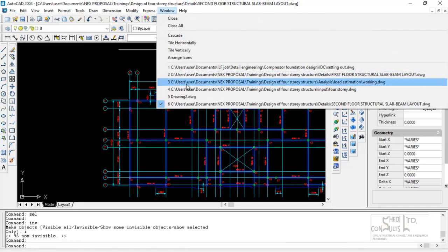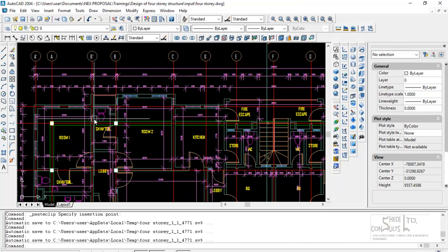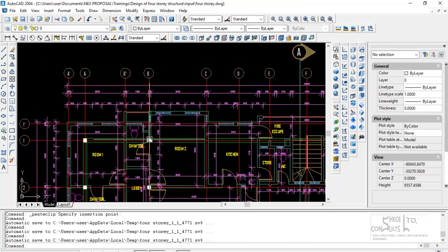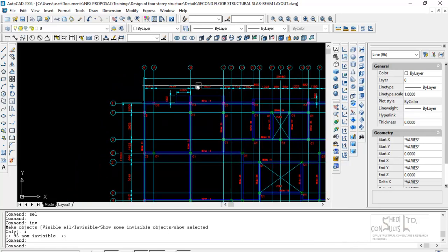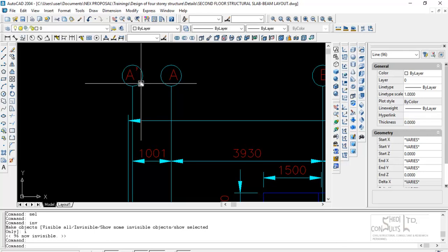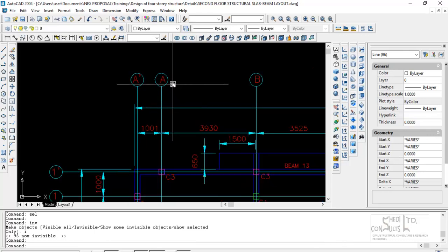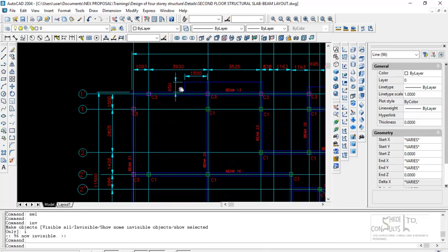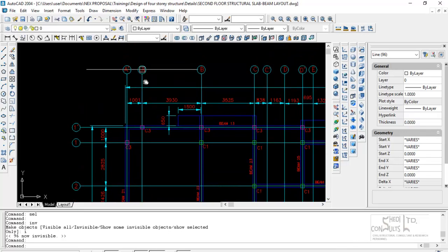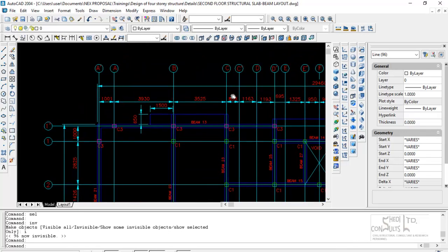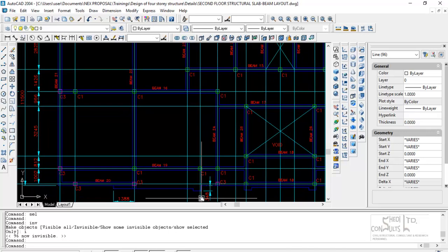If you look at the architectural design, it has A, B, C, D, and so on. You make sure your grading system follows the same sequence, and then where you have an additional structural entity, you indicate, it's best practice, you indicate with a similar identifier as that of what was shown on the architectural design for ease of construction and setting out. So we have A prime, B, C, C prime. We have a structural element there. That's what we call C prime.